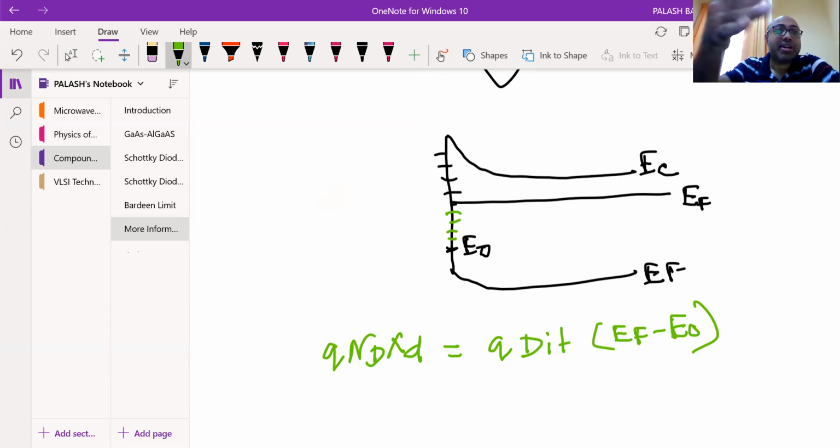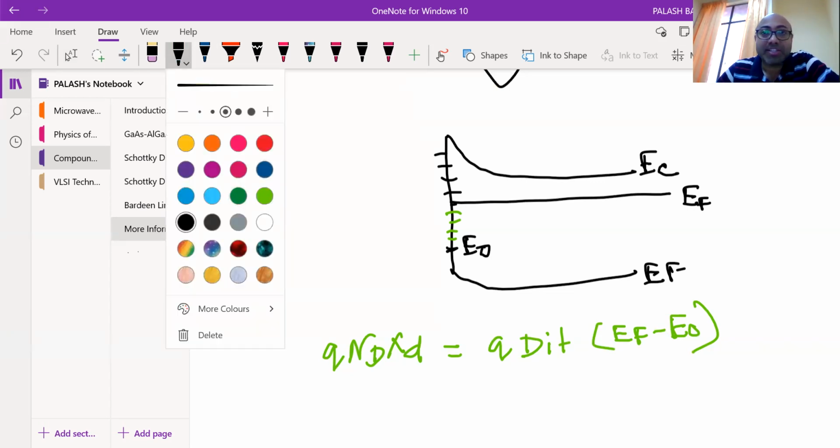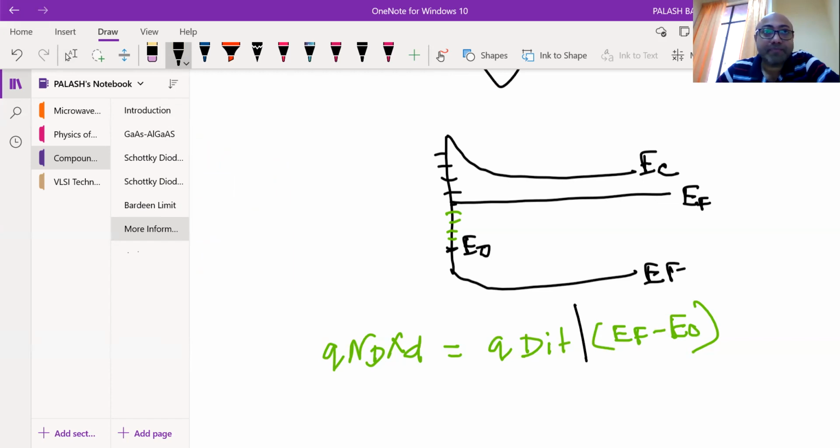I have given, the semiconductor has given this charge to that interface state. So in charge equilibrium, around 100 electrons have been provided by the semiconductor to the defects, right? So a total of 100 has actually been exchanged. That is point 2. Now you see that if your DIT is very, very high, your DIT is actually kind of fixed.